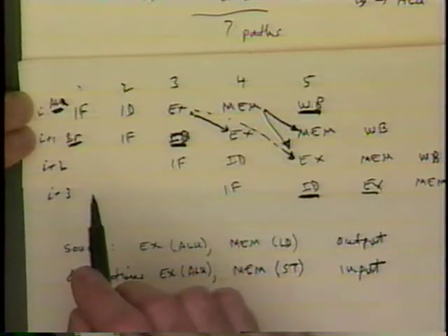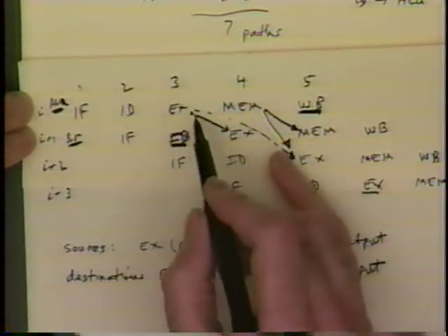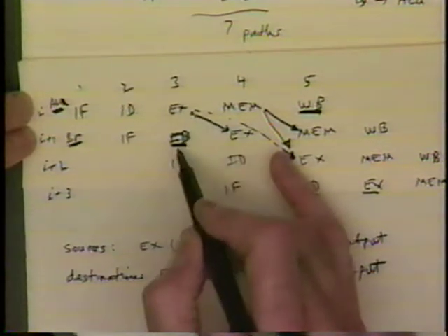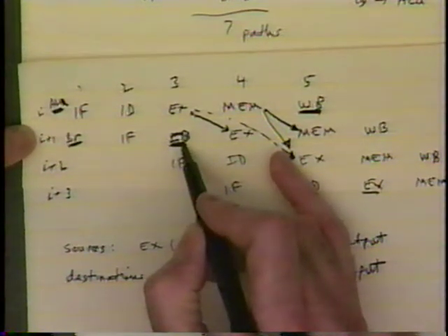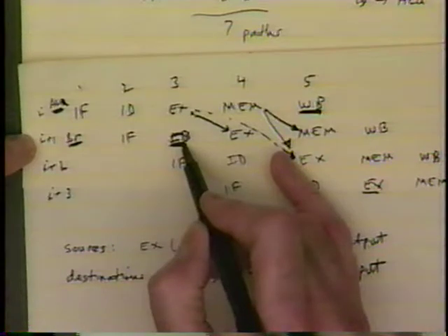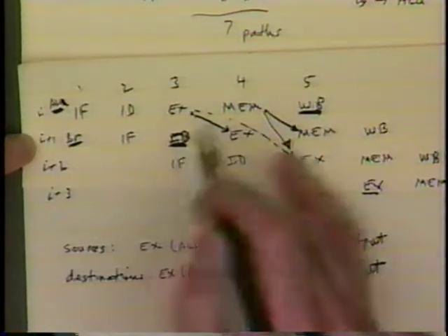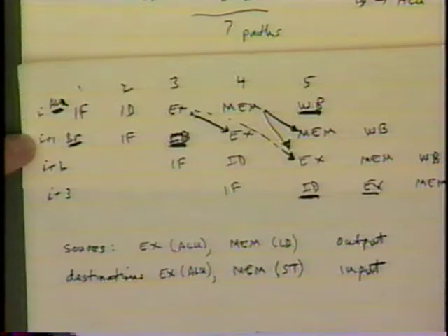Right. If you do an add where the result is in R1 and then you do a branch based on R1, yes, I guess you would need an additional cycle of delay there. Well, that depends on whether or not you're forwarding from the end of the cycle to the beginning, from end to end or beginning to beginning of cycles. Okay, good point. Last time you decided to forward from the end, and decided to avoid the forward stall. From end, right, because